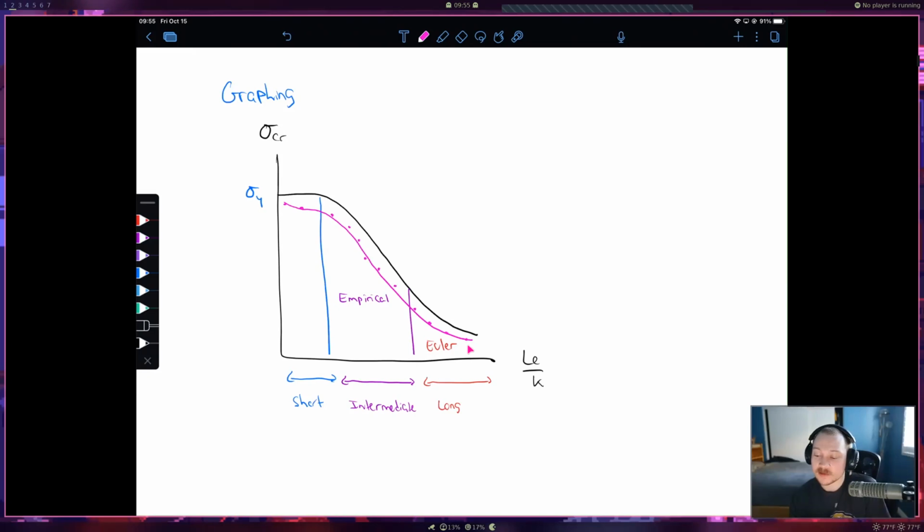So we'll be doing that, and I'll talk about this next week too, but the thumb wheel is still really sensitive. Maybe the technician can adjust this, I can't remember, but again, the thumb wheel is really sensitive. So if you're trying to just increase it by 10 pounds, you've got to barely adjust the thumb wheel. As is, even if you think you're hardly moving it, it's really easy to apply hundreds of pounds. So if we're doing the long columns, you could easily fracture it or have it fail from stability failure without even meaning to, because it's so sensitive. So I'll tell you that again before we start the lab next week.